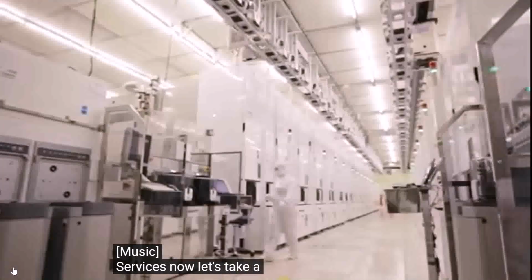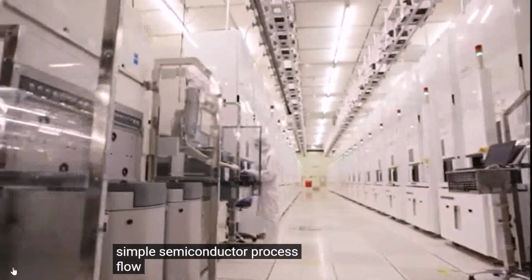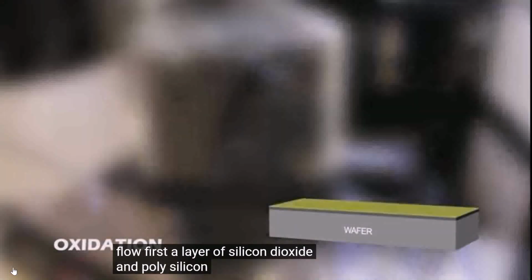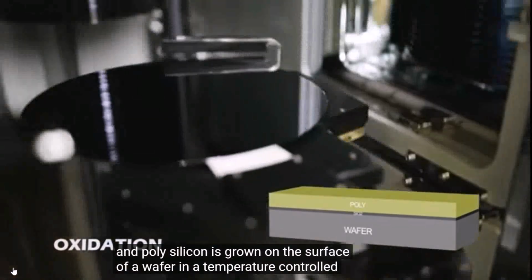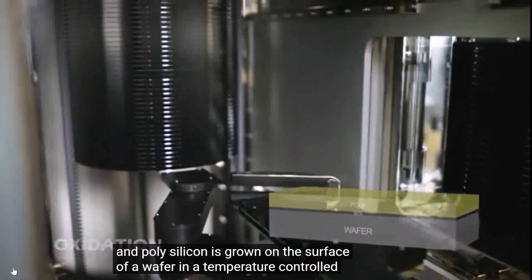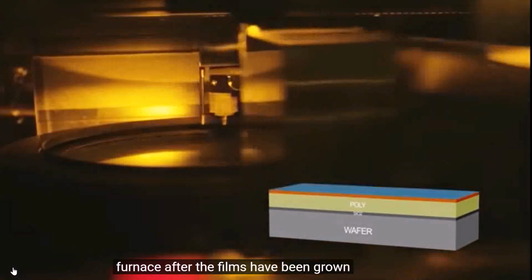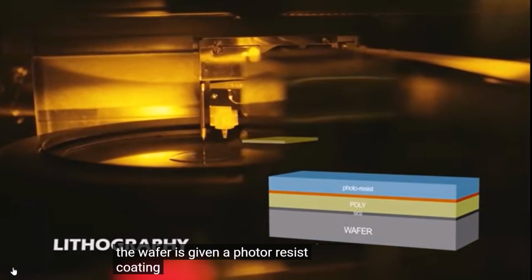Now, let's take a look at a simple semiconductor process flow. First, a layer of silicon dioxide and polysilicon is grown on the surface of a wafer in a temperature-controlled furnace. After the films have been grown, the wafer is given a photoresist coating.